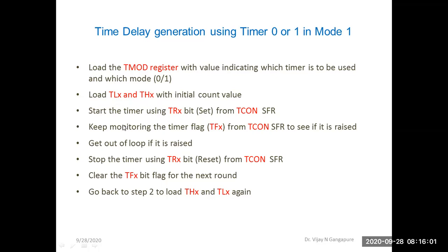Then after that, your job is just to monitor the TF flag bit, the timer flag bit. TF means timer flag bit. So TF0 or TF1, depending on which timer you are using, you have to monitor, and that TF bit is in TCON. That is, TF0 and TF1 bits are in TCON. So you have to keep monitoring to see if it is raised, which means if it is set.